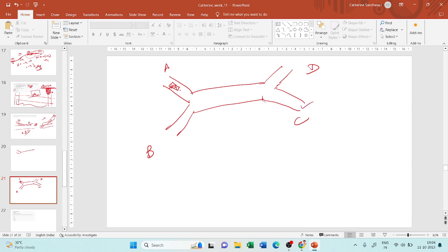I will first make the merging action, right? So I will merge from A and come to this mainstream. Let us call this main road E. Then after I've merged into this traffic, I will diverge from it and enter C. So here I have merged and here I have diverged. This is nothing but weaving. You merge and then diverge. So this is the weaving action.